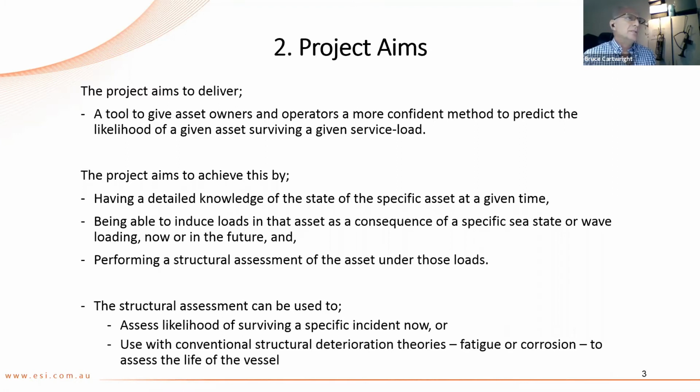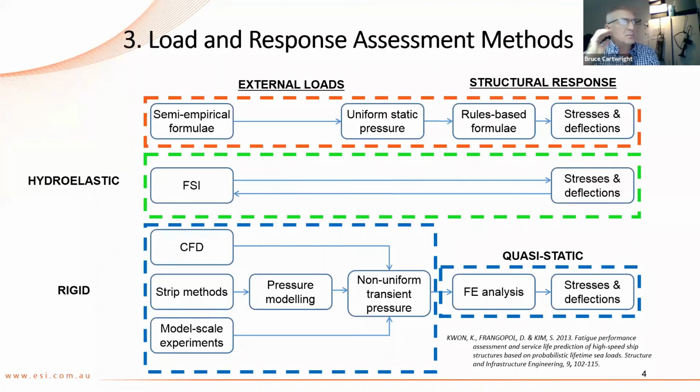And what we want to do is now perform a structural assessment of the boat with those sorts of defects in it and see how the degraded boat is going to respond to specific incidents of relatively high load, so limit state conditions, and run this sort of analysis with a known wave and look exactly at what's going to happen to the boat.